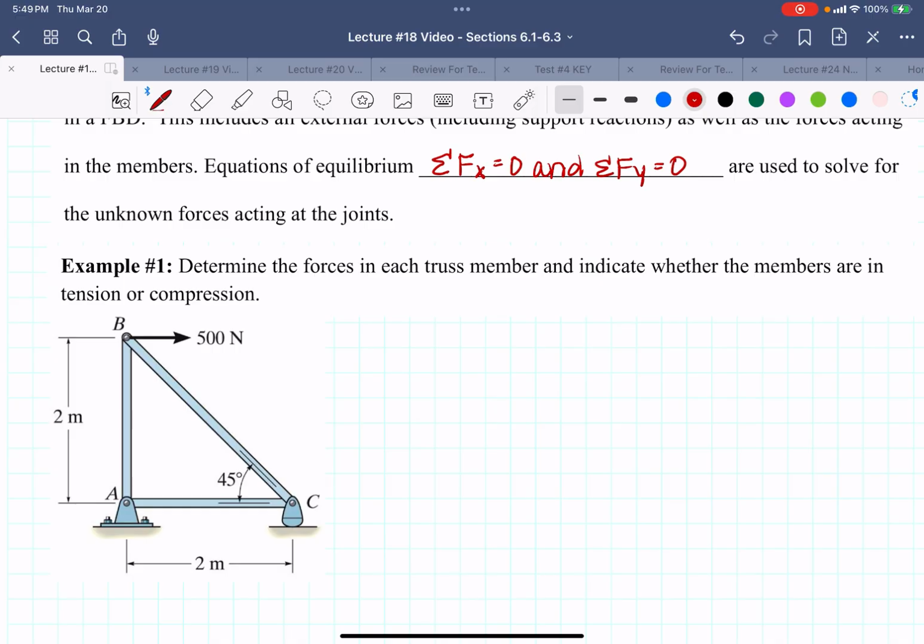So I have this truss here that's got 3 members. And it's got a rocker on one side and a smooth pin on the left side. So first what we're going to do for the method of joints is we are going to look at a joint. So let's start with joint B, because right now I'm not going to solve for the reaction forces.